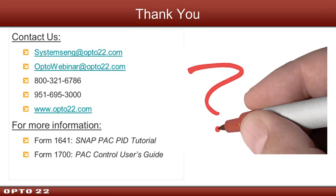Great. Mike is asking, will the PID settings, the PID values, on my temperature controllers transfer to the Opto settings? The answer is it depends. Obviously, it's going to depend on what formula your PID controller is using. Now, hopefully you've got a manual and you can look that up, and if it's the same as any of our velocity B or C, ISA, interacting or parallel, then the answer is yes.